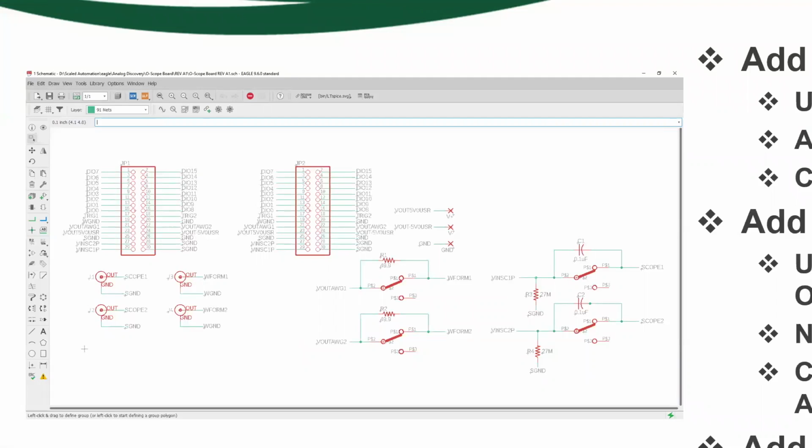And you give them names. And what's really cool about this program is that I don't have to draw from one to the other. I just give it the name and it knows to internally connect it. So it makes your drawing a whole lot cleaner and easier to see. So if I had to connect all those wires, you'd have a spaghetti mess and you wouldn't be able to see it. So that's what's really cool about using named nets, is that it saves a whole step there.